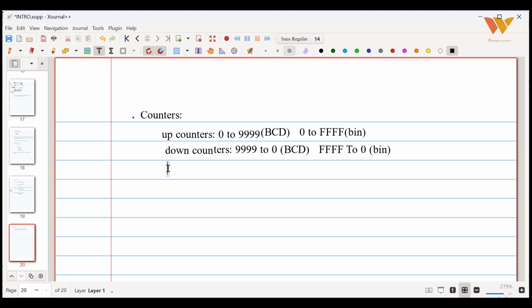Here in the Omron PLC, you have a counter and a reversible counter. You have two counters. It is called CNT here. This is a normal counter. Here the operation is in reverse order. As you have seen in timers, it was counting the value from 50 to 0. Here also the same thing. Even if it is an up counter, it will count from the maximum to 0.